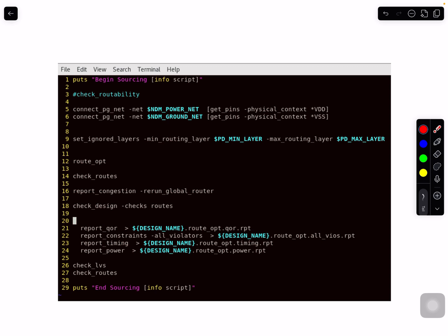Clear that? Okay, so you should have some code here, whether it's check routability or some other way, check legality or report CTS or something like that, at this stage. So that is a checking. In every flow, I always had a pre-check done. So you need to have a pre-check here. This is the other important thing to understand: connect PG net, or whatever tool you're using, should have something like this.